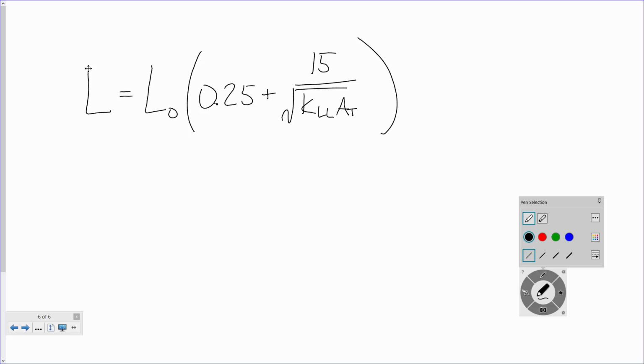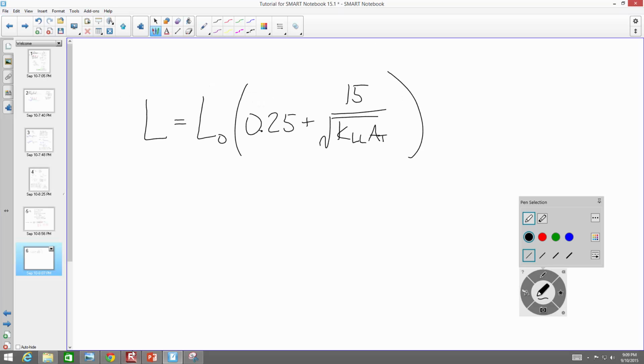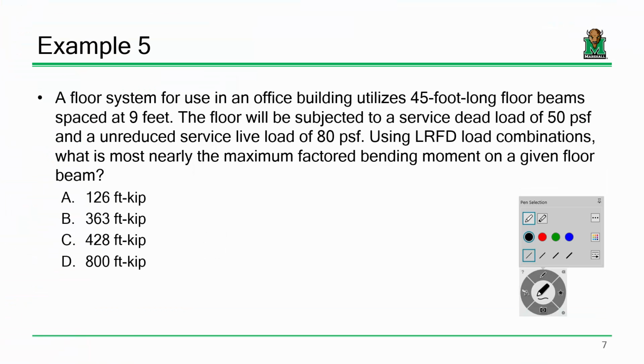based on the probability that we're not going to see all that design load throughout its design life, and that's live load reduction. When you get to concrete design and steel design, you end up using factored loads that hold 1.2 times the dead plus 1.6 times the live. Well, you have to calculate your dead loads and your live loads in order to use that, so that's what this problem is about. Because it technically is structural analysis. It's not design. Okay, so let's go through the problem.